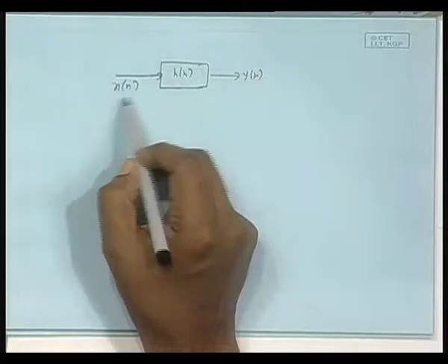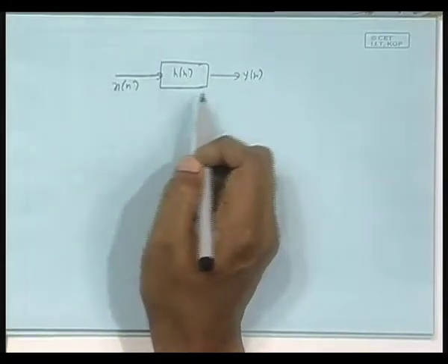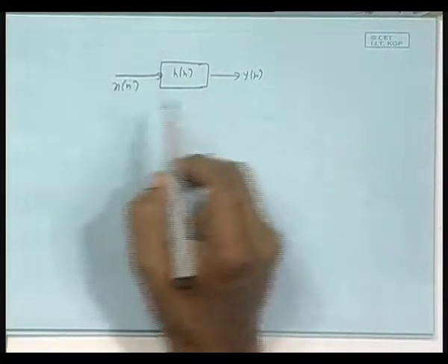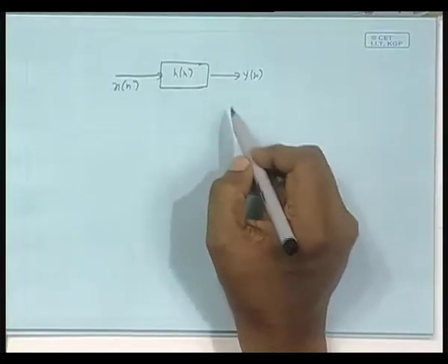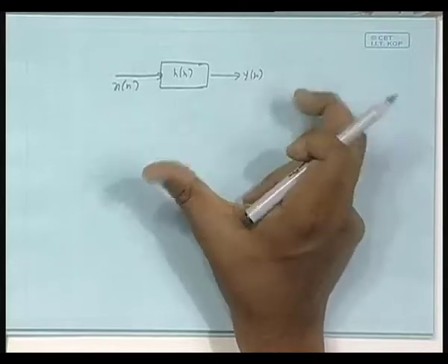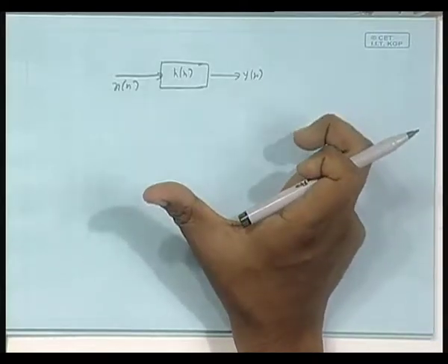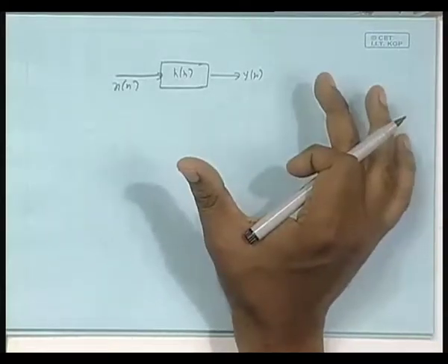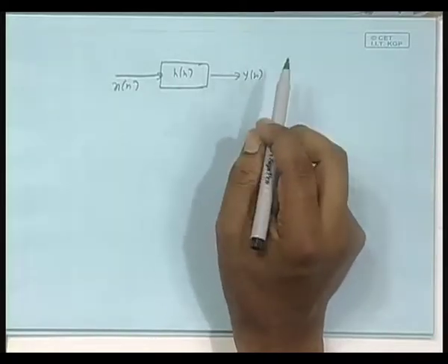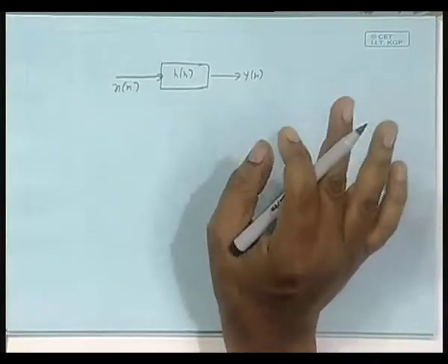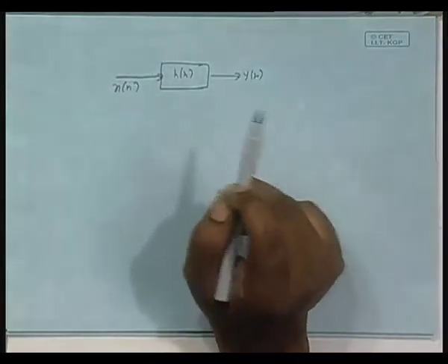So, I take the N-point DFT and multiply the two DFTs. That will again be a sample of the DTFT of this, but if I take the inverse DFT of those samples, I do not get y n, because y n is a longer sequence; its length is not capital N, it is 2N minus 1, ranging from 0 to 2N minus 2. Then the question was, even if I do not care for that, I still persist with this: I will do X k into H k and take the IDFT.